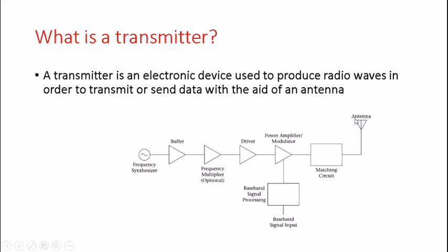But a simple explanation of a transmitter is that it's a device that performs a modulation scheme on our desired signal, which we are trying to send, by firstly frequency shifting that signal, then amplifying it to finally send it to that antenna. And as we know, any signal that we are trying to send needs to undergo modulation first, which is only frequency shifting our signal to a higher frequency. The reason why we use modulation is to decrease the length of this antenna.